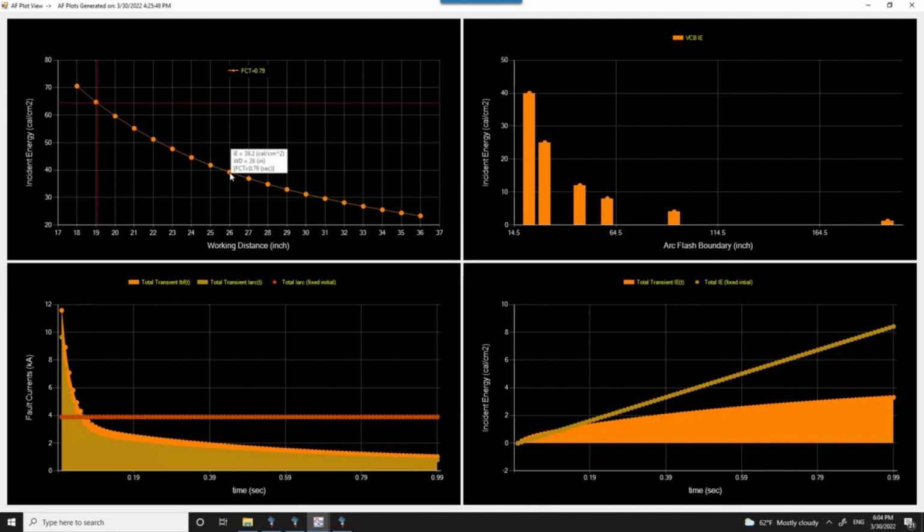So the bottom line is, with the use of the calculator along with the protection and coordination settings for Arcflash, the results of incident energy could be easily evaluated without rerunning the study in ETAP for all the different facilities or all the different faulted locations per se.